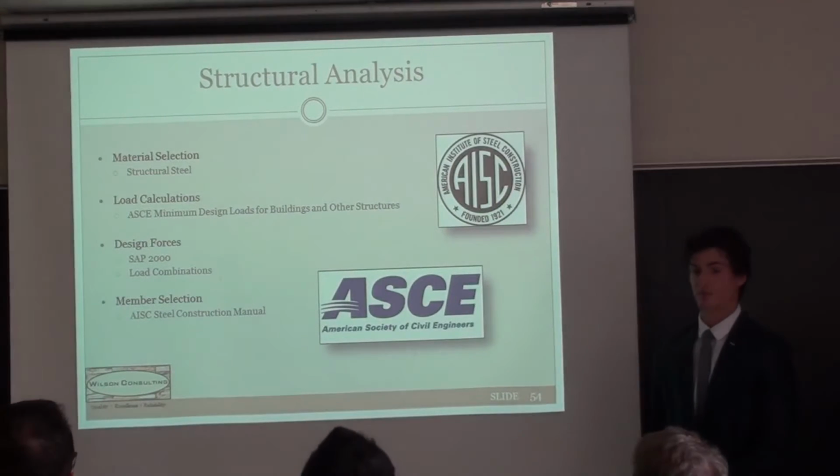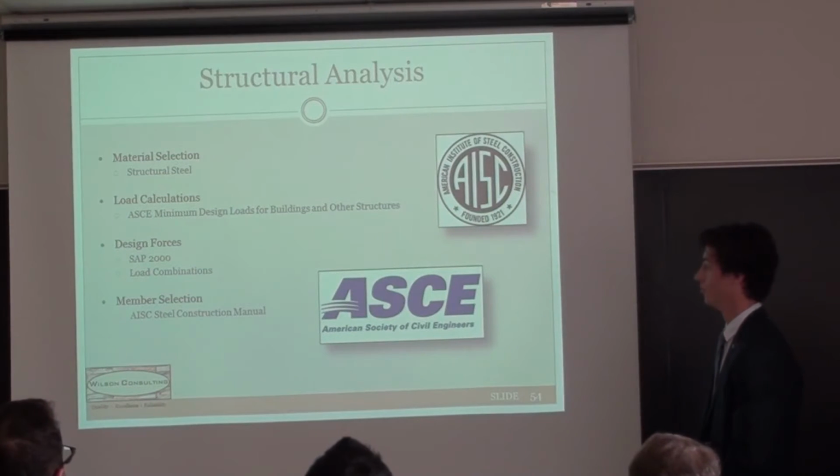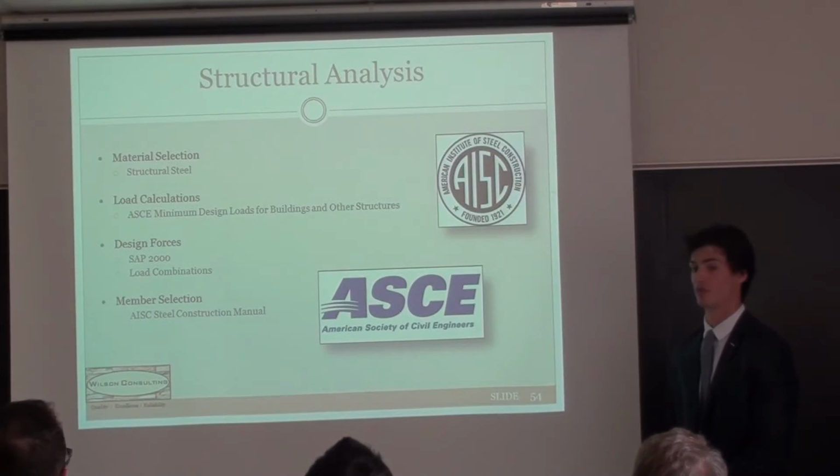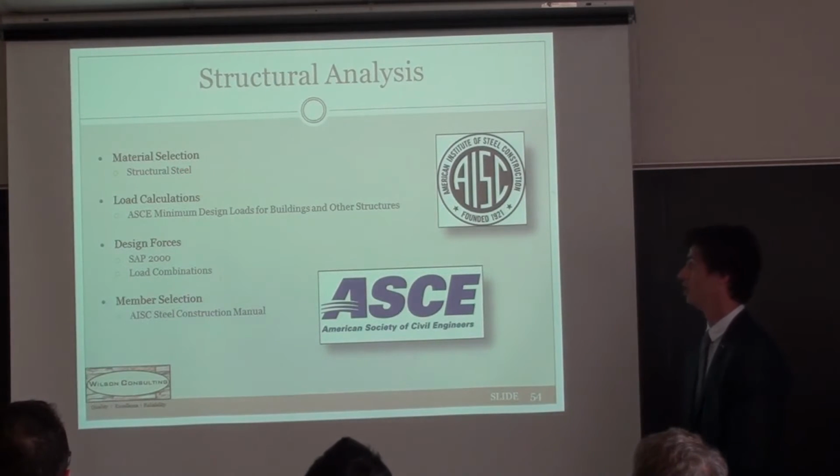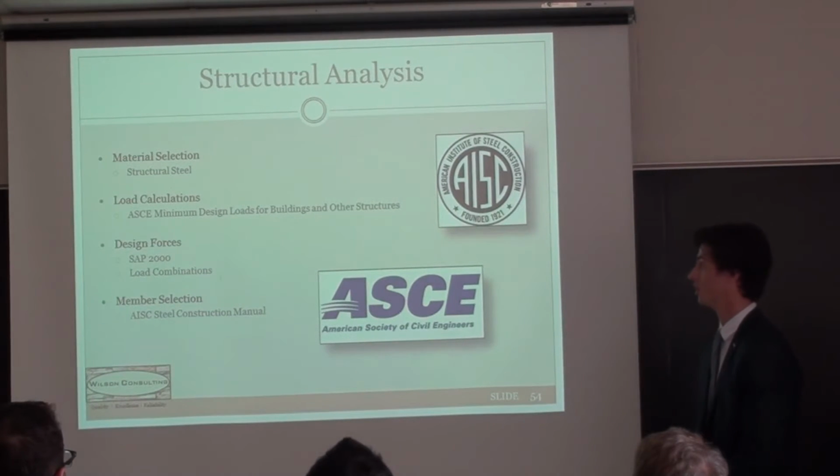The structural analysis was the main piece of my part of the project. As I said before, we chose steel. Material selection was the first part. We chose steel over concrete for its high strength per unit weight, its ductility, uniformity, and speed of construction.